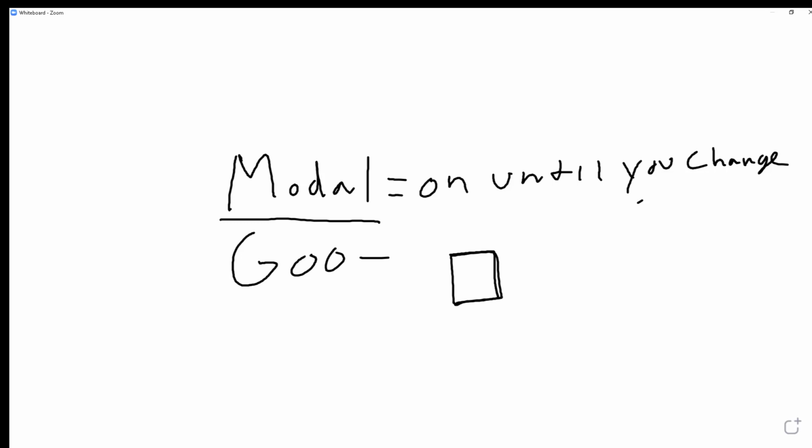So let's take a look at, just so I can show you here, the M codes. M codes start on page 19 in the handout, and it goes through all the different ones you have, and these all apply to the HAAS machine specifically. Some machines have different codes depending on what brand they are. So some machines may use standard M codes, some machines may have T codes, etc. It depends on what brand machine you're working with.